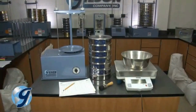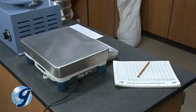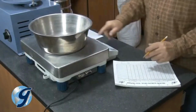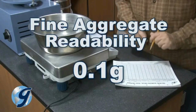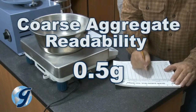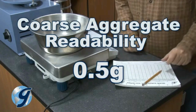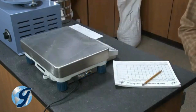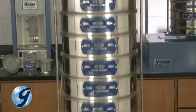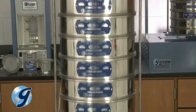Devices required for this test method are a balance or scale used in testing of fine and coarse aggregates with a readability of 0.1 grams for fine aggregate and 0.5 grams for coarse aggregate or mixture of fine and coarse aggregates. Test sieves that conform to ASTM E11 specifications.